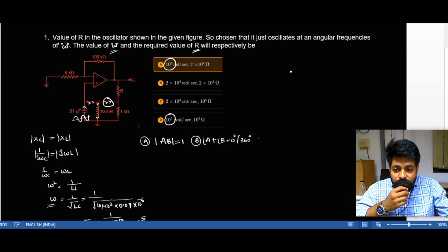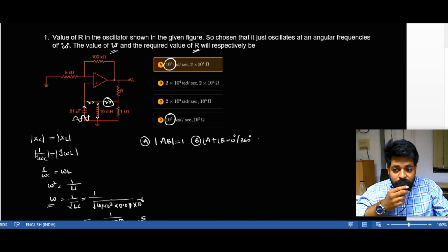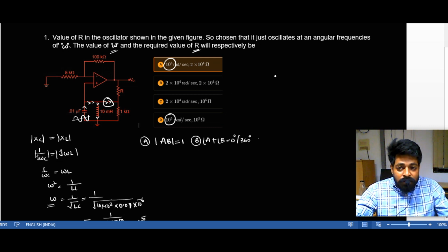be simplifying the circuit with some modifications, where I observed that the tank circuit is under resonance. No current will be flowing into the circuit from outside, and from the outside no current is flowing into the tank circuit, meaning it is totally detached. But whatever oscillations are generated across the particular tank circuit may be provided, but the current will be zero across the other branches of the inductor, so that it will be like an open circuit.